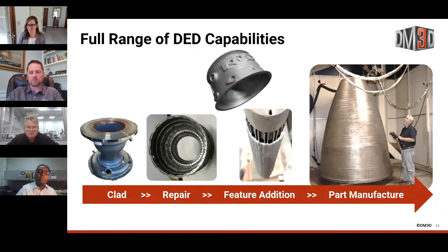Here, the copper chamber was first built using powder bed fusion process, and then we applied Inconel on the outer surface of this and built flanges and everything there. So this is a cladding operation more than a perfect multi-material, but potentially you could print this copper and Inconel at the same time in the single build and get unique benefits out of that. But like everything else, it has got its own challenges.